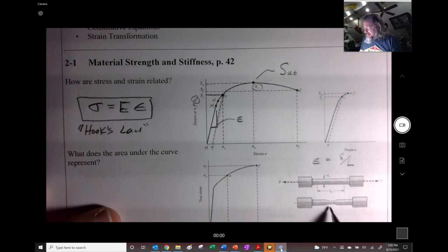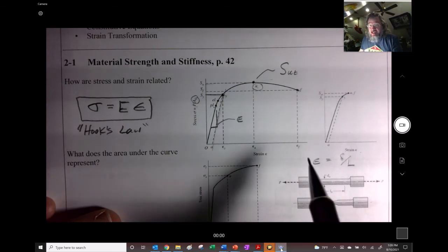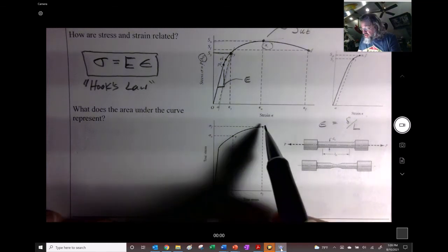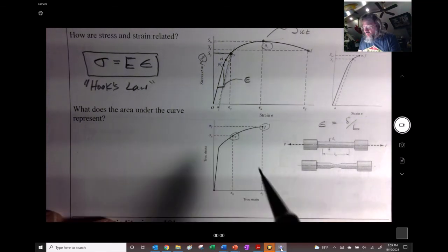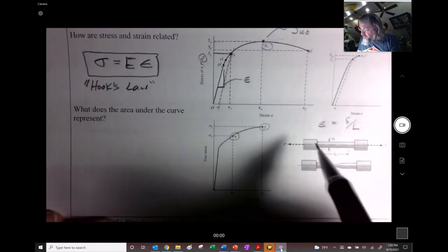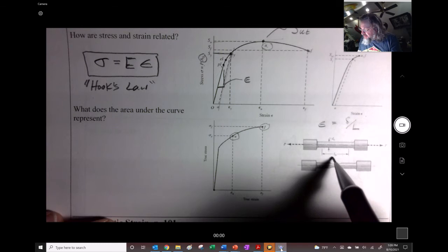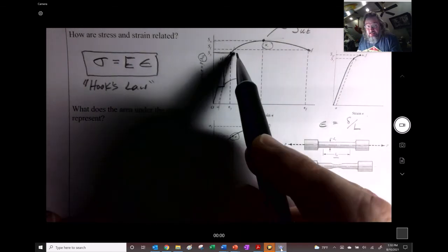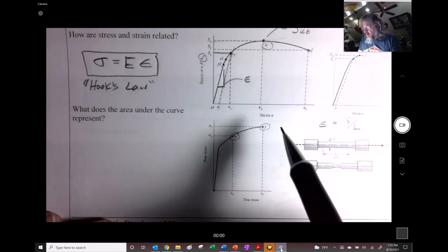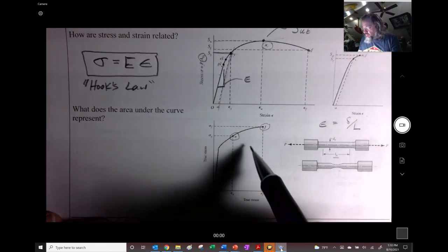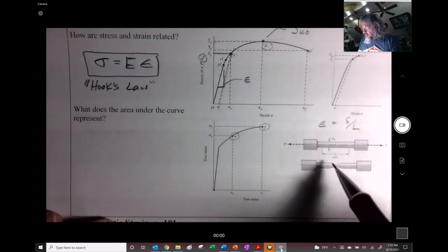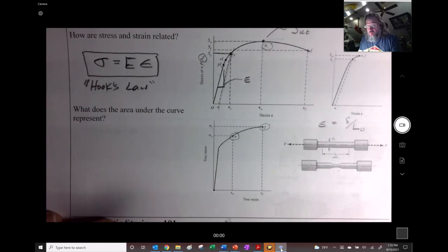But because of necking that's taking place, the actual stress that takes place is this one right here, as we start to see. And we can see that fracture is above ultimate right here. The same thing is actually true for the strain. We might use the length of the thing. We might want to update what that length is as we're taking data and we're coming along, and it won't be stretched out nearly as far because the actual strain that was taking place in between two different things isn't necessarily going to be based on that original length right there.